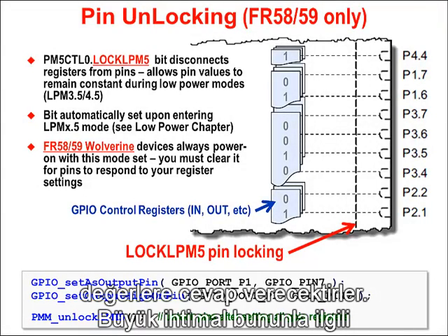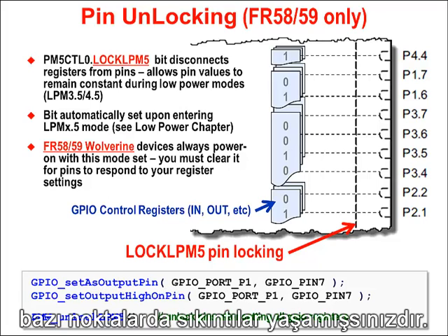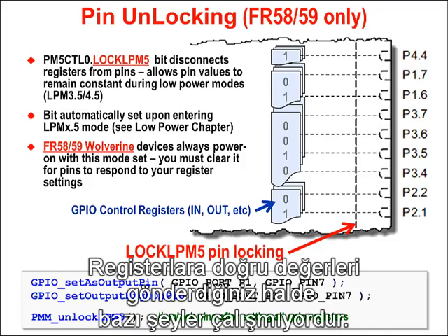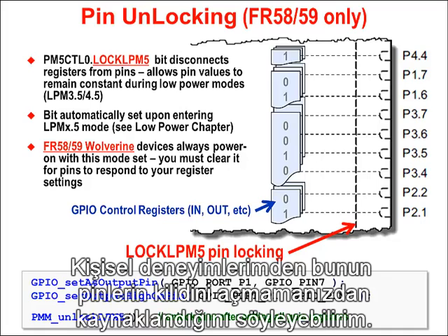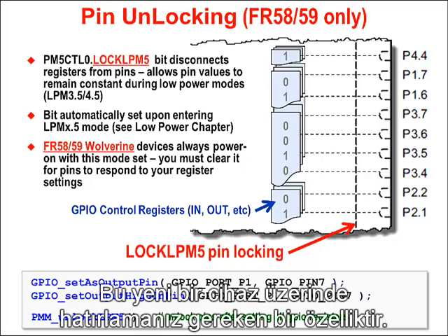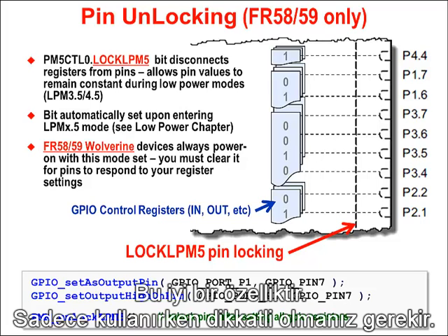You'll probably get burned with this at some point along the line. I don't know why the LED's just not flashing. I don't know what's going on. I know I set the registers right. I can just say that from personal experience. And you go, oh, that's right. Forgot all about that. Got to unlock the pins. So it's just one of those things that you have to remember to do on these new devices. It is a nice feature. It's just you have to be careful that you make sure you do this.